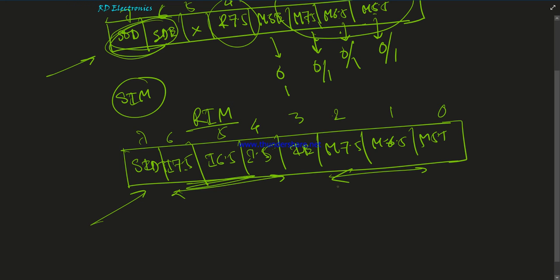These 3 bits are used to read the interrupt mask, and it loads the accumulator with 8 bits indicating the current status. So this information comes from the interrupt status and is loaded into the 8085. That's why it is called read interrupt mask, to sense the pending interrupt status.